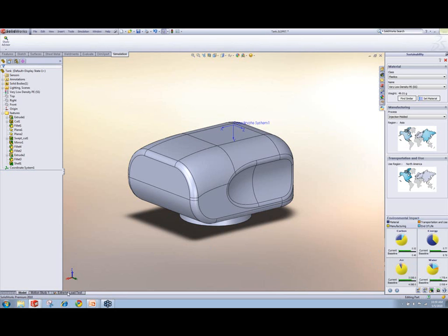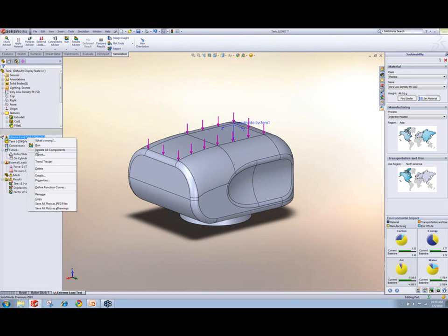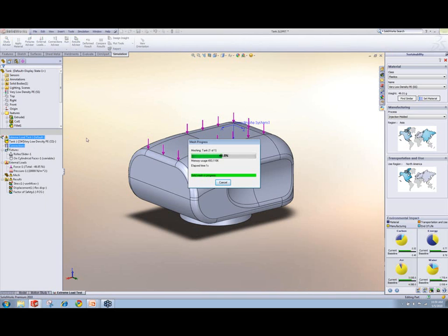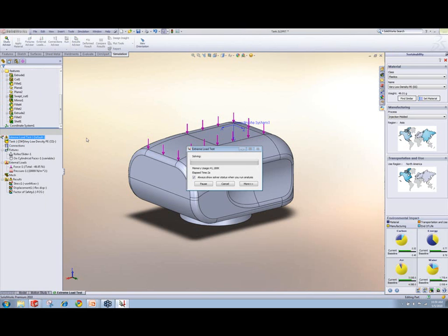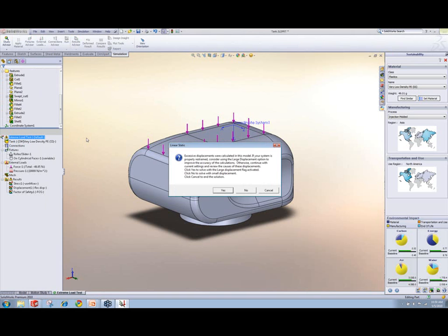Now let's make sure that for our study, we update our geometry here as well. We're going to rerun with the new thickness on the shell and see what our factor of safety is. So the bottom line is you want to keep on doing this. It's a methodical process you'll go through until you're satisfied with a factor of safety or a criteria that you've been looking at.